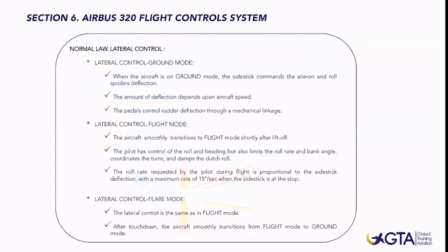As I was saying, you will practice this in the memory item for the ground proximity warning system. When you disconnect the autopilot and apply full back side stick deflection, you will see that the flight director bars disappear as soon as you pass 25 degrees nose up.